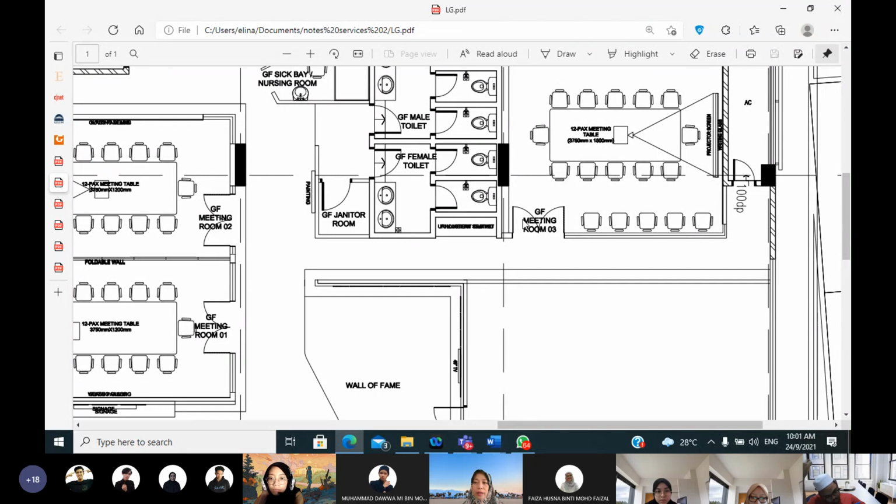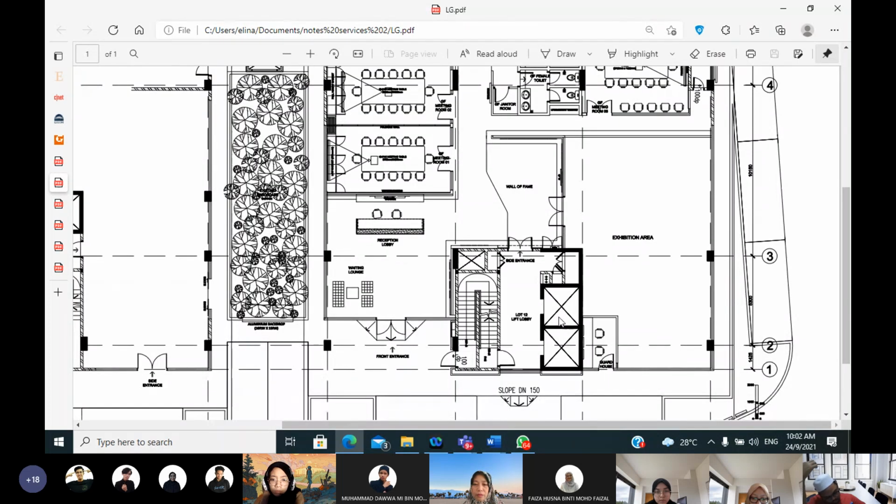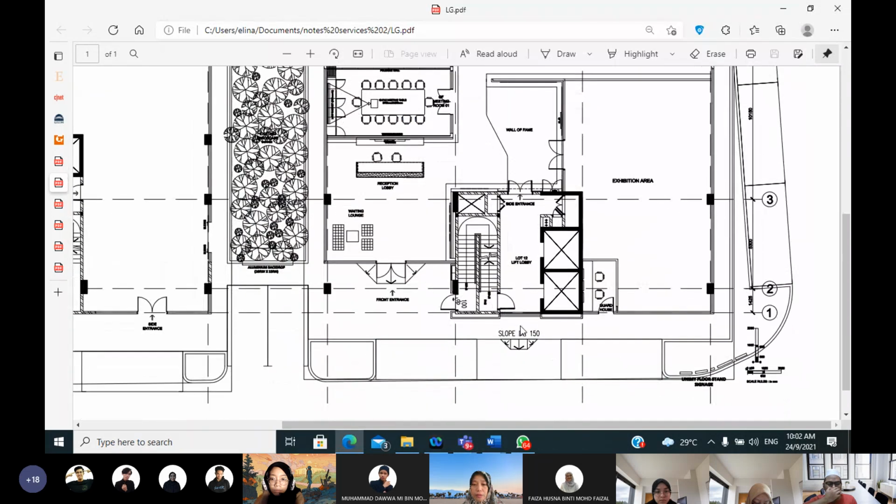So, how to start to allocate all those firefighting equipment? Okay. So number one, of course, you need to design the core area because the building is not only 1 storey, it's 2 storeys and above. So what you should do is design the fire staircase here and also your lift. So this is your lift core, and this is the fire door here.